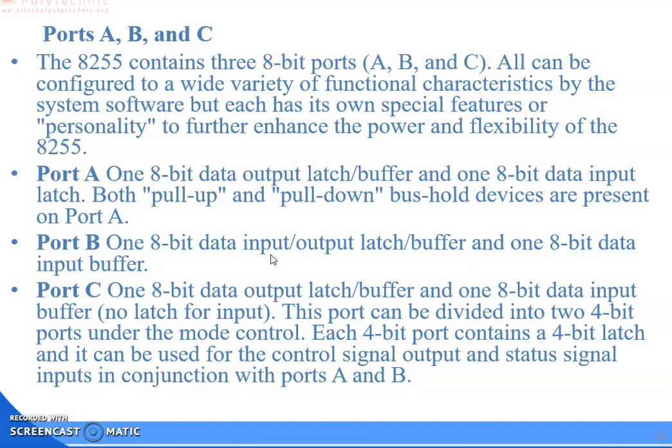Port A has one 8-bit data output latch or buffer, and one 8-bit data input latch. Both pull-up and pull-down bus hold devices are present on port A.